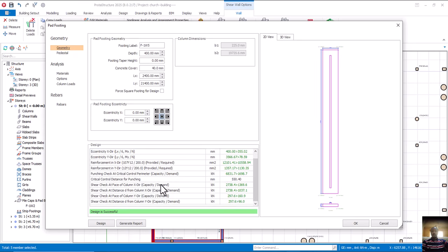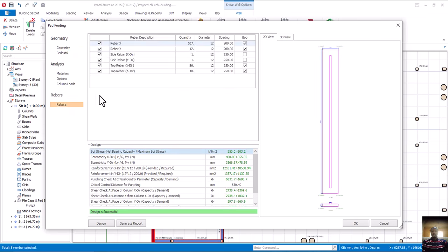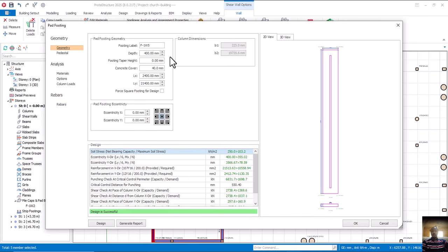So you can imagine. To be on the safer side, I prefer using Y16, so that even though the reinforcement is substandard, it still takes care of the failure that might occur. So that is that. Okay, come back here again. Let me see, can I reduce? So you can see you have to make some adjustments.